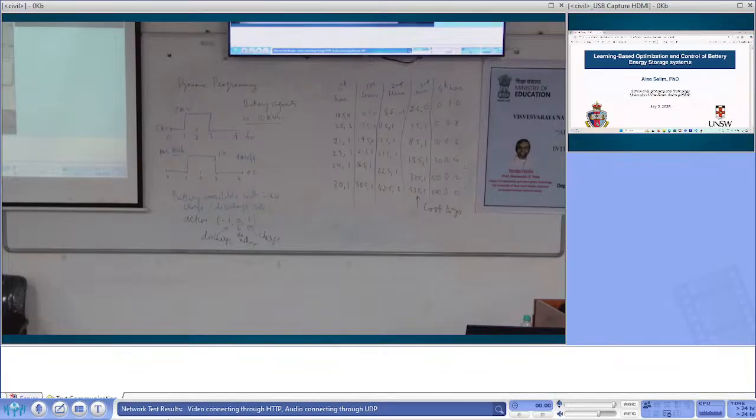Now, if you have a DC to DC converter with, say, 4 energy storage elements, what will be the order of the state? 4th order, right? And what are the possible values each state can take? Like duty cycle, what is the possible value each current or voltage in that device can take? How many levels of current or voltage can there be in each device?